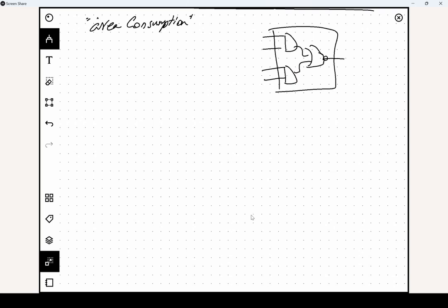Of course, there are other ones like the OR-invert, or AND without the invert, and many different configurations, for example where one of the inputs doesn't go to the OR gates at all. You implement something like this, and then another module, and just counting the number of cells is not the best way to do it. Another option is that you have a particular library and look at the area of each cell.